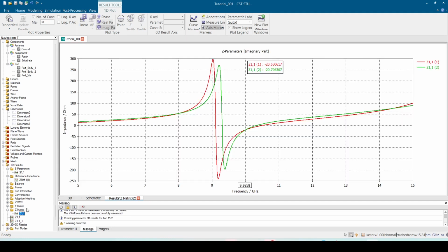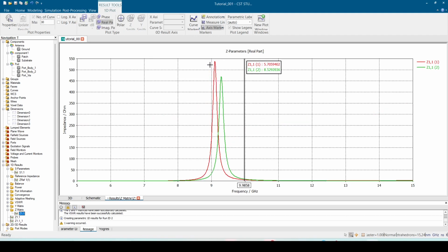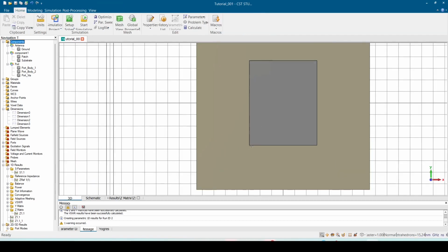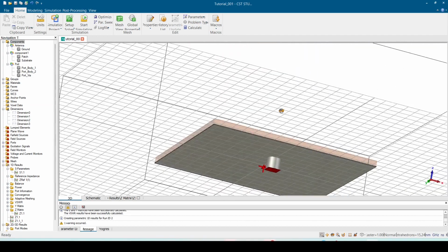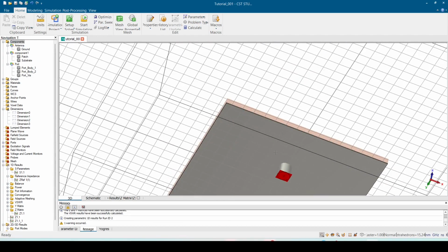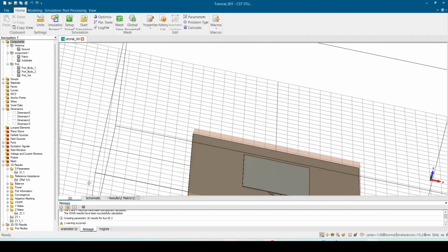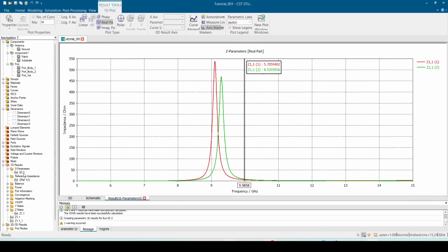Oh yeah, not the Z, the Z parameter. So here we can see that little bit of shifting of the resonances. Why? Because we changed the cavity itself. For example, if we have this as a cavity, now we increased the opening, right? And increasing the opening makes the cavity look somehow smaller, and that's why the resonances come a bit to the higher frequencies.